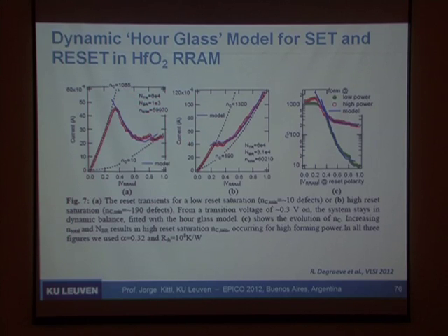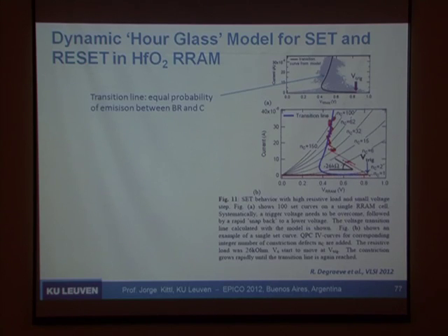What's this bottom reservoir? When you're forming, you're injecting vacancies down into the bottom reservoir, that's the idea. If you do a very strong form, you make a wide filament, and you have a lot of vacancies in your bottom reservoir, and then you saturate quite early and you cannot go into a higher resistance state. And this is a narrower filament. So I encourage you to look at this and hopefully bring criticism.